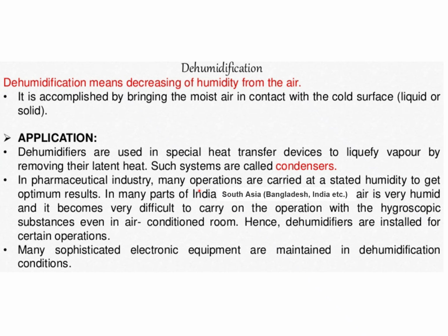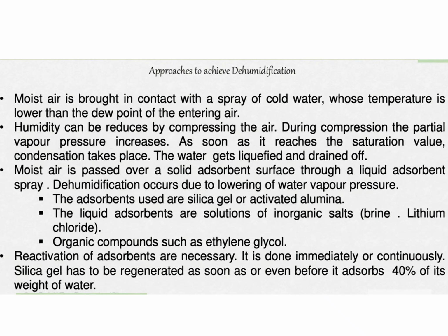In the pharmaceutical industry, many operations are carried out at stated humidity to get optimum results. In many parts of India, air is very humid and it becomes very difficult to carry on operations with hygroscopic substances even in an air conditioned room. Hence, dehumidifiers are installed for certain operations. Many sophisticated electronic equipments are maintained in dehumidified conditions. Moist air is brought in contact with a spray of cold water whose temperature is lower than the dew point of the entering air. These are the approaches of dehumidification.